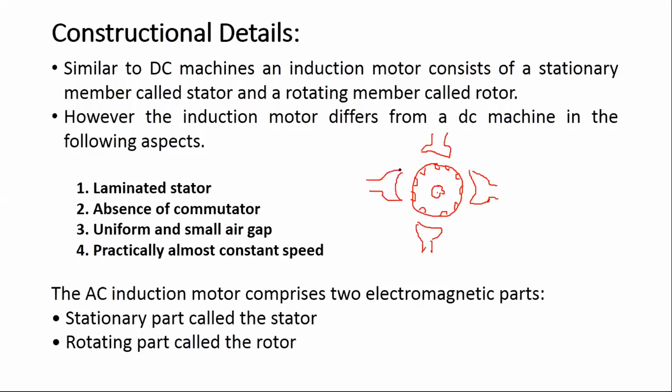So you have pole shoes, like this is a 4-pole machine which I have drawn here. The windings are wound over each pole, and the windings are connected either in series or shunt with the armature, or we have a separately excited DC machine.